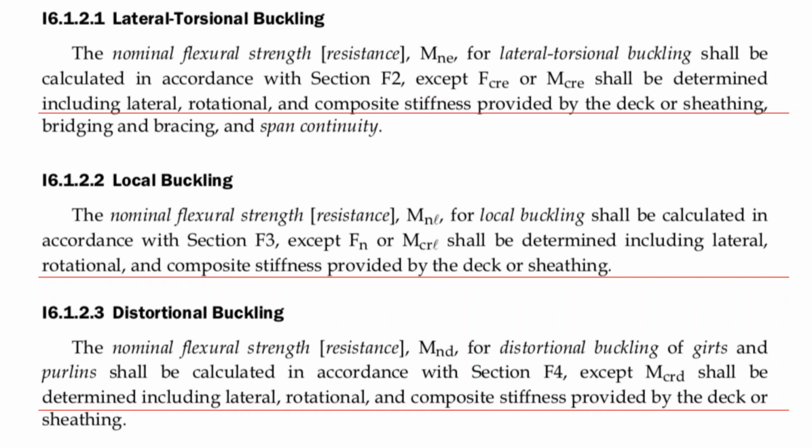roof, and considering all of these important limit states that most of you have heard about, especially if you're working in cold form steel, especially local buckling and distortional buckling, which is very common in these types of thin walled open cross sections. So we're setting up the example to work within this framework of considering the connectivity of the purlin to the roof sheathing or the roof panels, and considering that as a system.